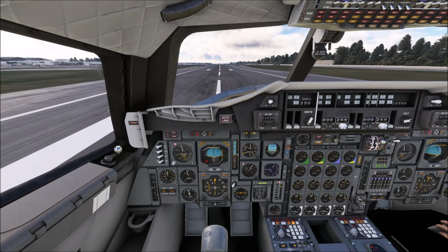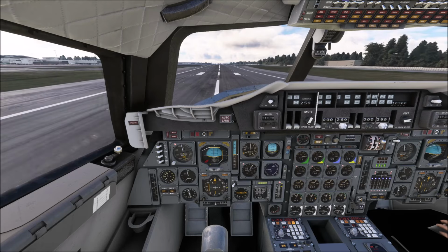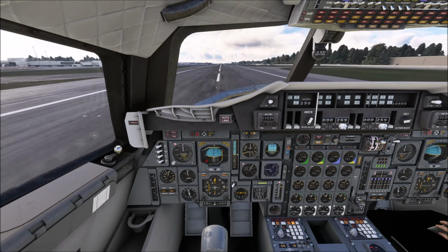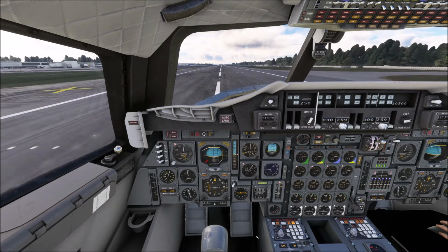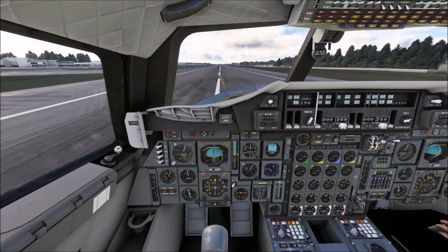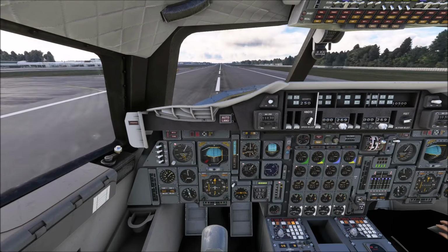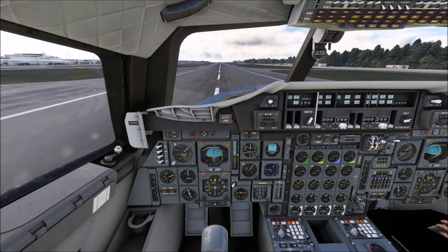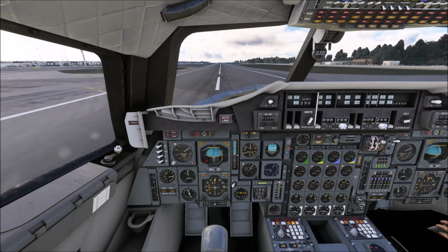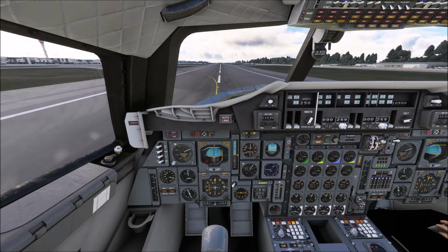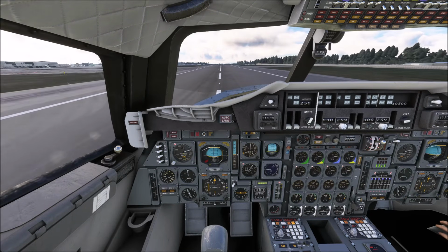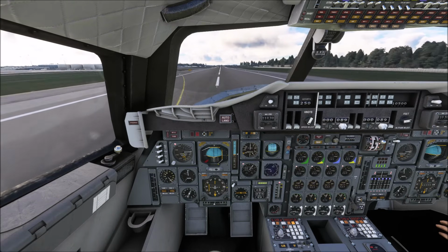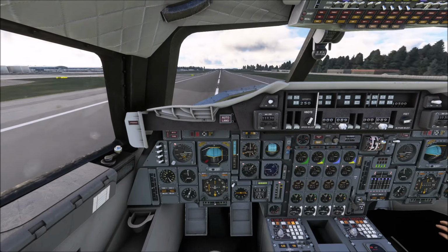I'll get this show on the road, get the aircraft airborne, cleaned up. Autopilot engaged, and then we'll start the business of monitoring the climb out. Keeping on the centre line, a little bit of left rudder, a little bit of crosswind there. Looking for 170 knots, 160, 170. Stick fully back, waiting for the nose to rise. There she goes.